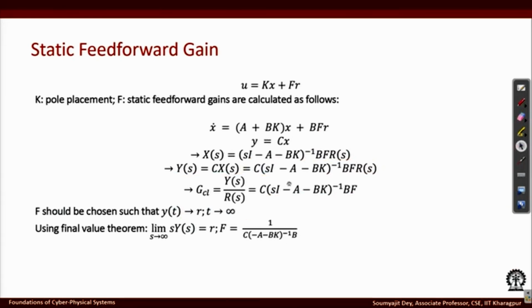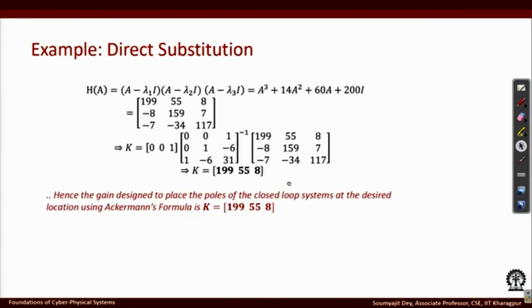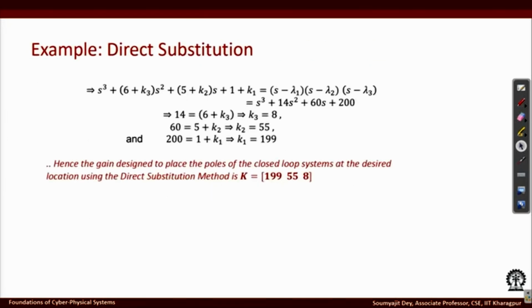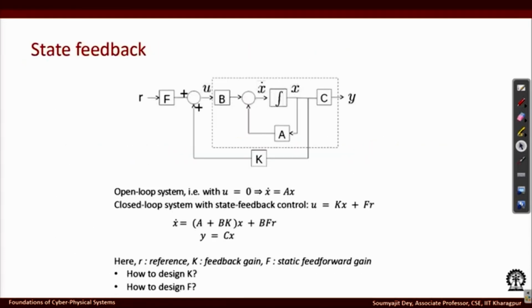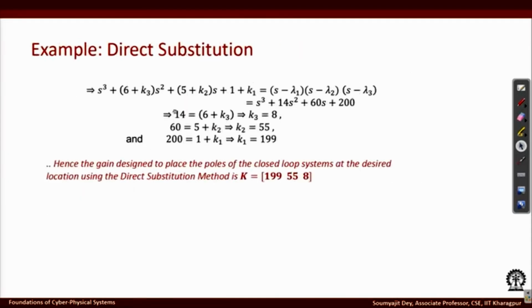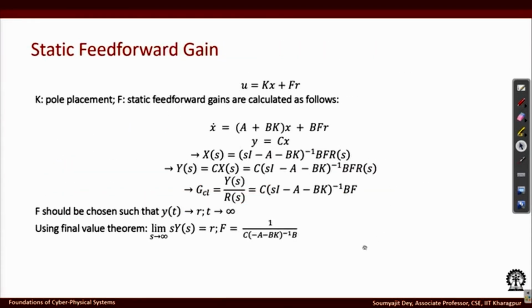In case you really have the reference, because if you remember, when we did the earlier part we considered the reference to be 0, but of course it is possible that you have a reference signal, and in that case you will need this feed forward gain, and the way you can design this feed forward gain is to use this formula right here. So with this we will end the lecture here. Thank you.